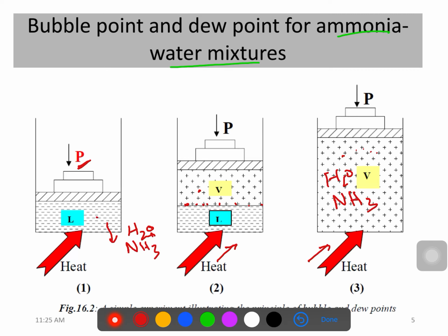will go to a condenser, expansion valve, evaporator, which will basically reduce the capacity of the system. So this heat transfer will become non isothermal, heat transfer non isothermal हो जाएगा. Evaporator temperature will increase, evaporator का temperature increase हो जाएगा. Evaporation will not be complete, evaporation complete नहीं हो पाएगी.